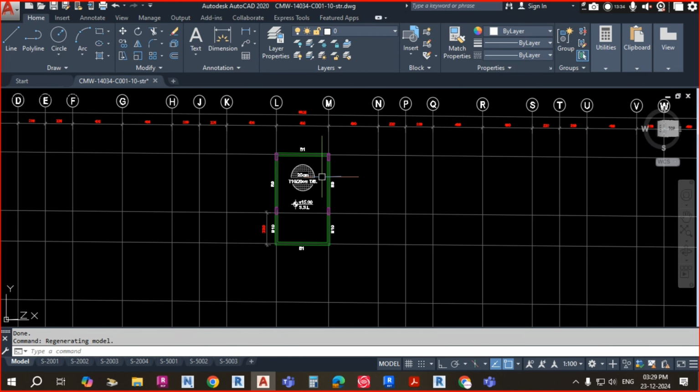So like that, on each and every floor you have to go and check that the column is coming and up to which floor it is moving. Base floor is okay, because the base level is foundation, so we are able to place the column in foundation. But where this column is moving, you have to check from all the drawings. Maybe some columns stop below some levels, some columns go continuously up to the top level. So this way we have to work it out for the column.